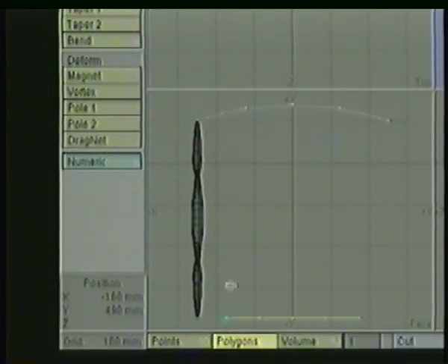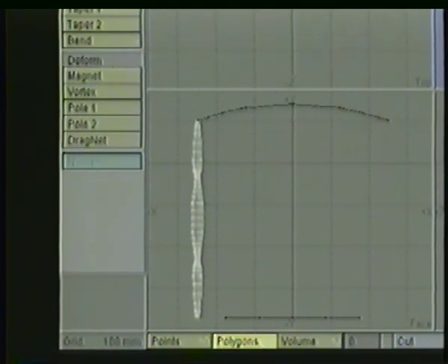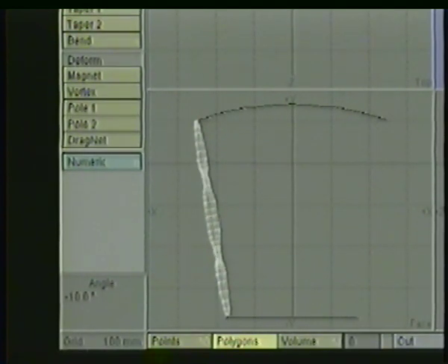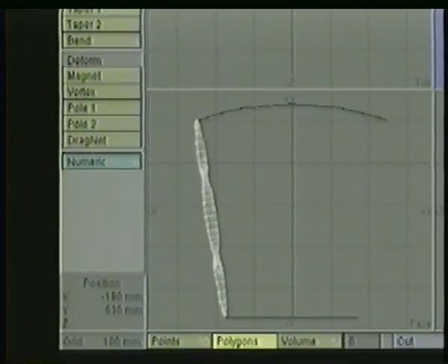That's where I think they should come to, about there. This also means I should probably rotate and position my upright post. So I'll swap layers one more time with the apostrophe key, and I'm going to start by rotating this curve. I'll put my cursor where I want the rotation to occur from, right there, and I'll rotate this so it's down toward the end. And that's pretty close.